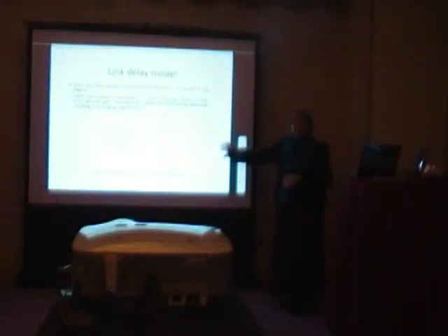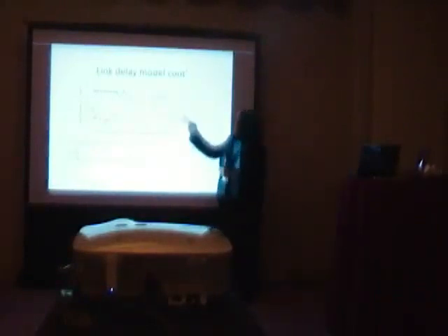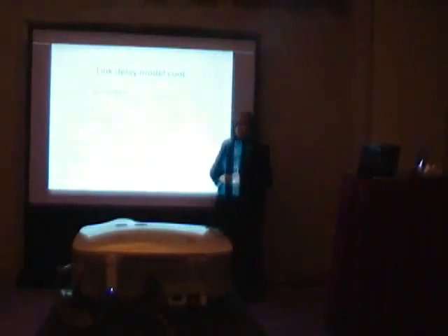On the circuit level, the link is considered as a driver and repeater with a wire that has interconnect resistance and capacitance. On the layout level, each interconnect can be considered as a signal carrying conductor and the ground plane. Between the signal carrying conductor and the ground plane, there will be signal capacitance, plane to plane capacitance or interlayer capacitance, coupling capacitance, and fringing capacitance. Those capacitances will affect the delay.